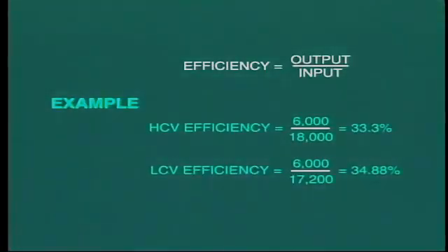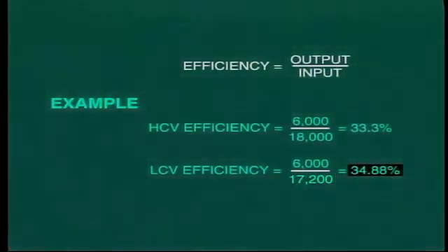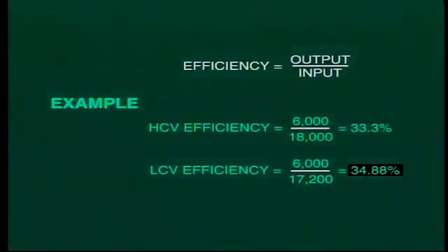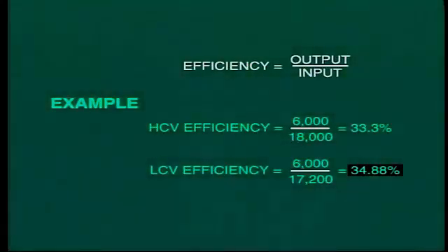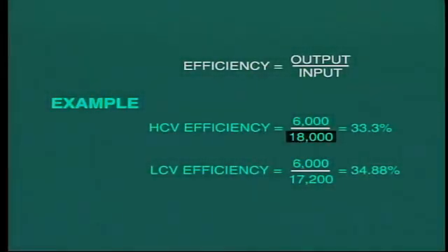In fact, as we know, other heat losses are far greater than this amount. However, beware, in many other situations, for example, in many European plants and European manufactured equipment, the quoted efficiency is based on the lower calorific value. This would, of course, provide an apparent higher number for efficiency. Clearly, if the heat input to the plant is indicated at a higher value, then the calculated efficiency would come